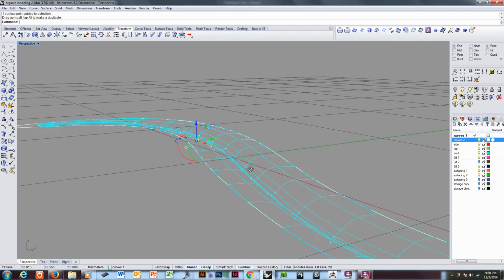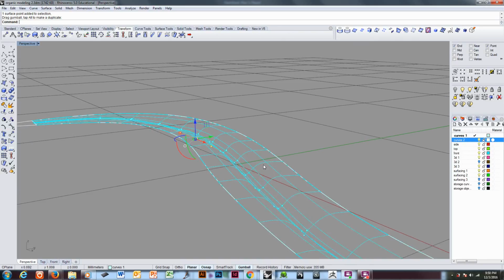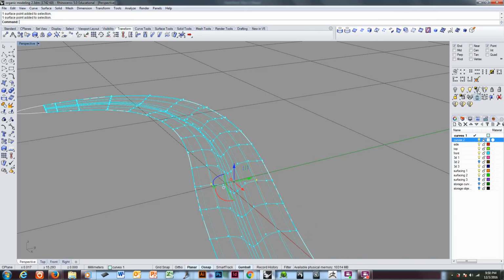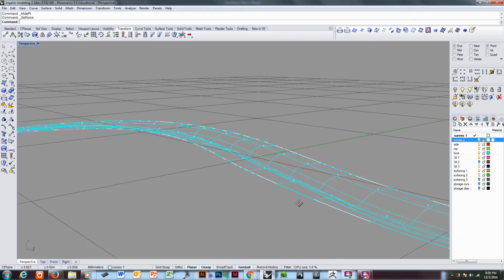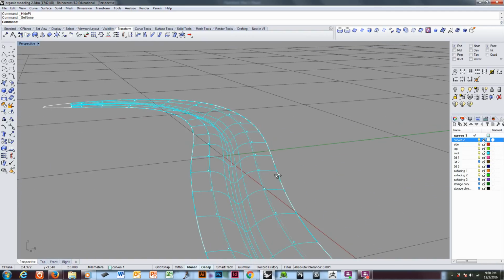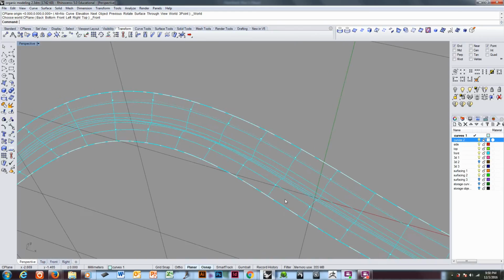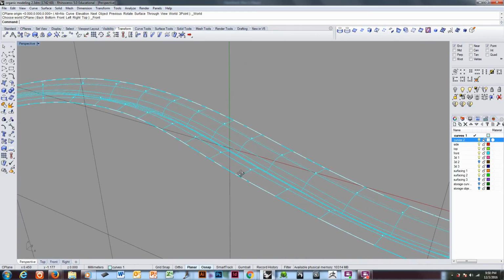Now, I did have an idea about swelling it here a little bit. So, if I want to remember where I'm looking, I'm going to keep my mouse right here. So when I turn off the points, and I turn on the points, I know where I want. I want right here and here. I want those points turned on. Invert, select, hide, turn off gumball. I'll go ahead and activate my front C-plane because I do prefer moving with a vertical C-plane over gumball.